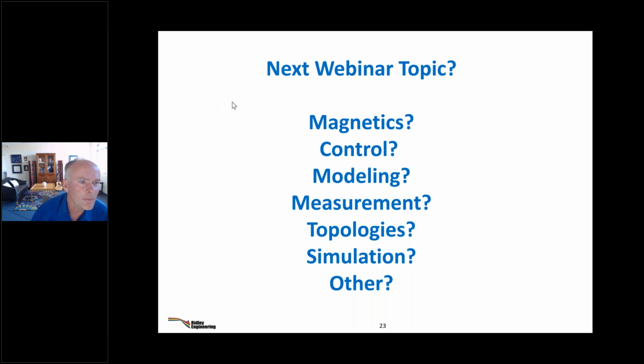How can you do current mode control of the LLC? Good question. Go look up some papers on that. People are doing current mode. They've got little current sensors in there. They actually put 2 caps in, and they look at the voltage on the cap, and they do some integrators. They build current observers, and they get the dynamics of current mode control. It's really, really interesting. Nobody has begun to model current mode control, and you won't.